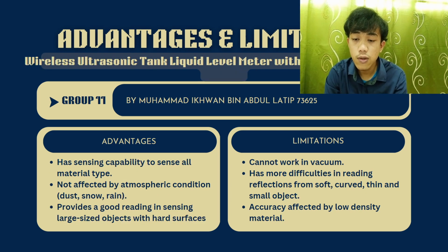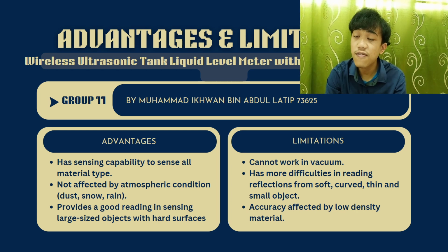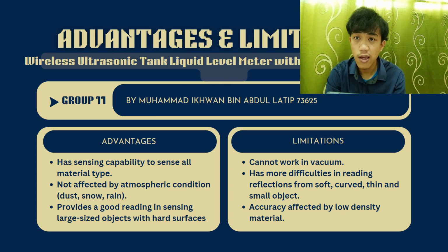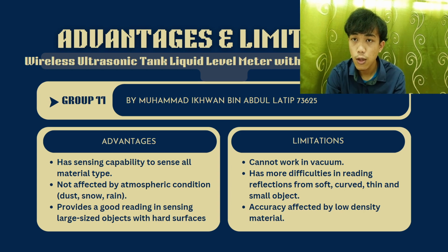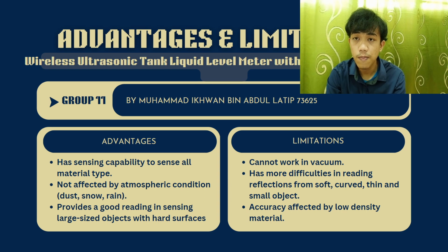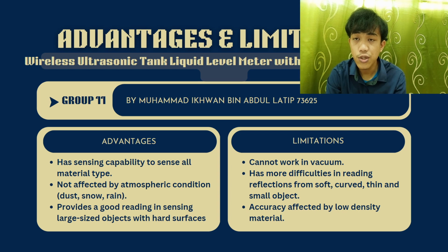For the wireless ultrasonic tank-like level meter with temperature sensor, the advantages are that it has the sensing capability to sense all material types. It is also not affected by atmospheric conditions such as dust, snow, rain, and so on. It also provides a good reading in sensing large objects with hard surfaces because the sensor can convert sounds bounced from the object into an electrical signal, which gives units.